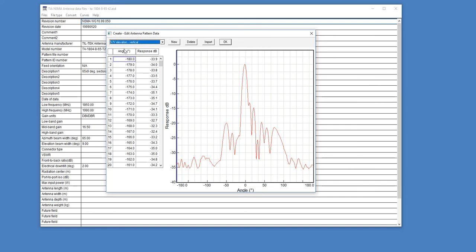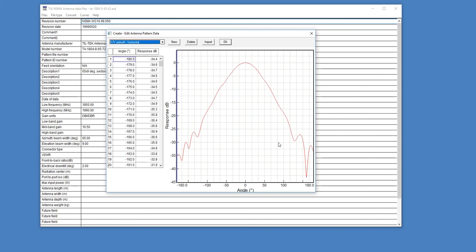And we'll point out that the elevation pattern in particular is very important, because you may have a BTS that's covering a large area, but you also want to be able to pick up signals from sites close in, so you don't want to just overshoot with your antennas. So the elevation pattern gives you the ability to calculate the signal level that gets to the close in sites, whereas the azimuth pattern tends to influence more the signal level that gets to the far out sites. So that's very critical in this application.